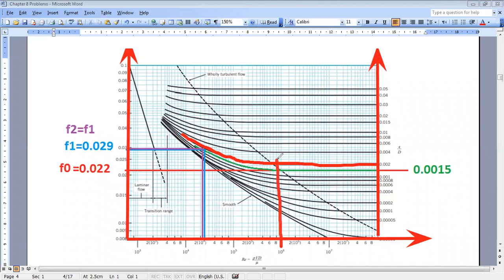When I reach the intersection point, it will give me the corresponding value of f. So now I take a new line from the intersection point towards my axis, and I can read the corresponding value of f. And I can give you, for example, f and Reynolds, and you get epsilon over d. So you have several possibilities. Depending on your input, you decide on the output.